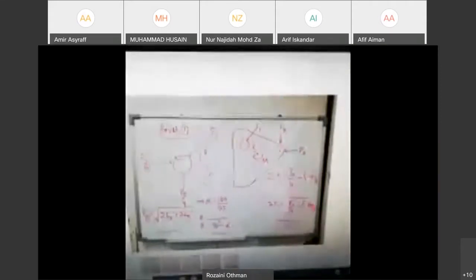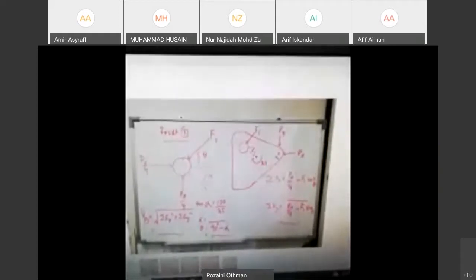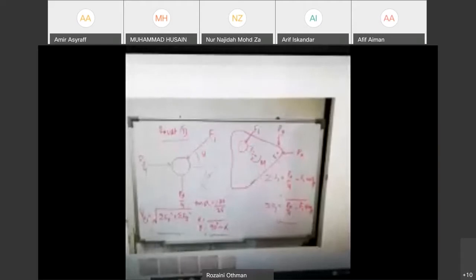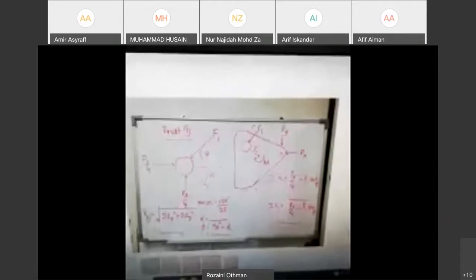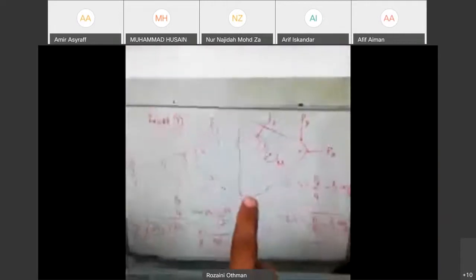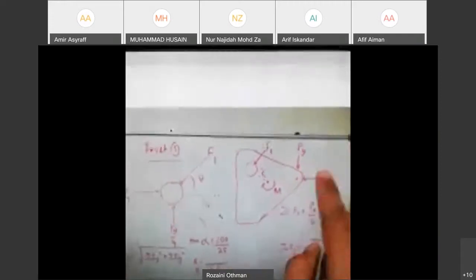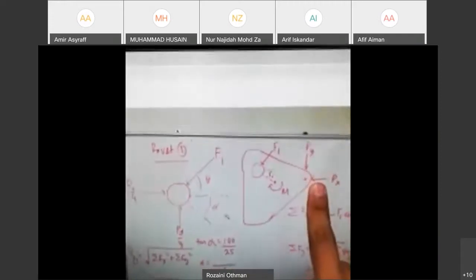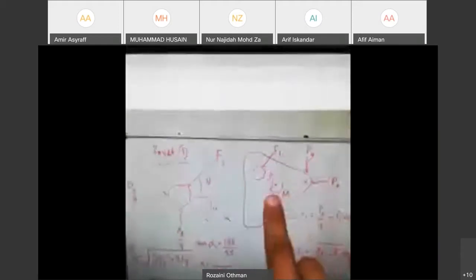So basically, in rivet number one, we know from the figures, from the gusset, the bracket, that we have two forces, direct shear force, Px and Py, right? And then from there we will get the moment, right? And then this F1 is the tangential force, right?